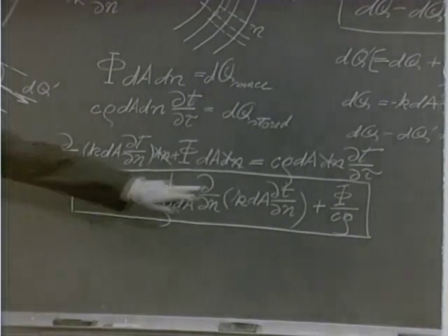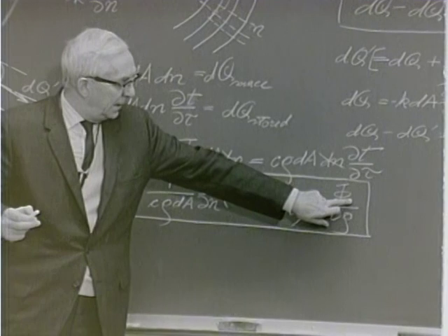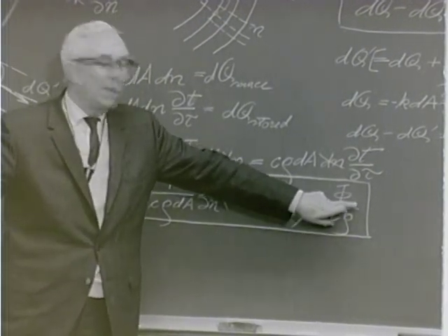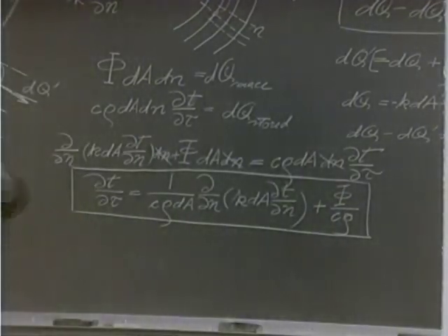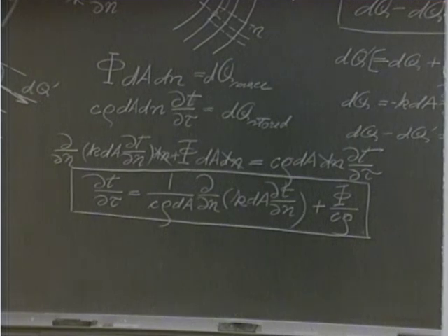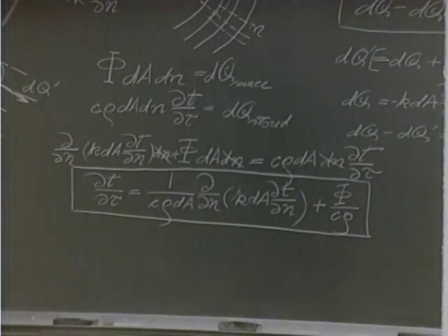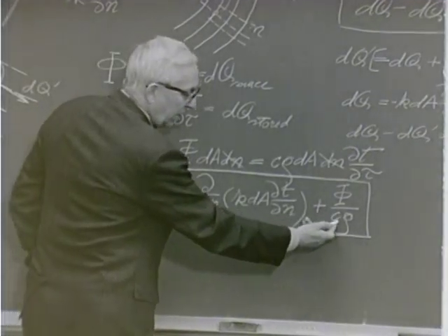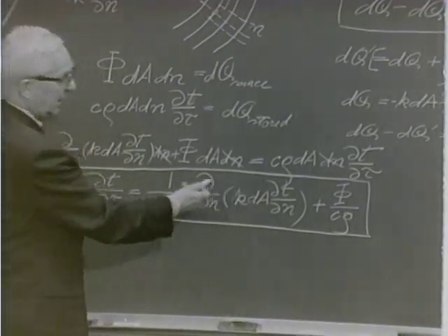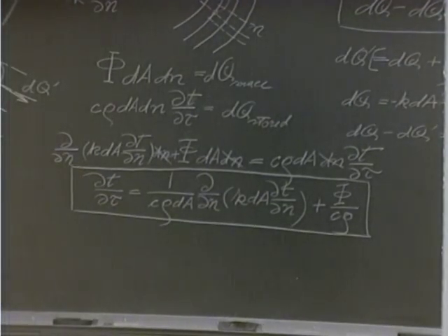Maybe I can just point out, of course, in order to make any kind of calculation on the effect of heat conduction, I have to know the heat source. I would have to know what kind of chemical reactions occur and what is the heat generated or absorbed by such. I have to know the material, which means then I can, from reference books, take values for specific heat, for density, for thermal conductivity, which are all properties of the material involved.